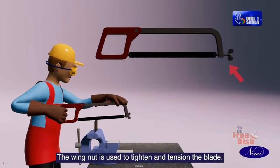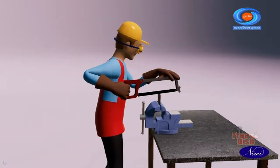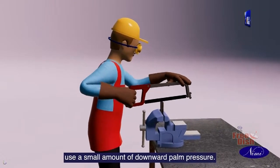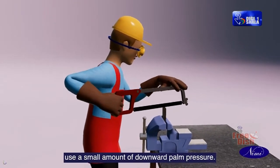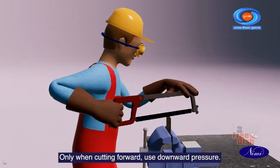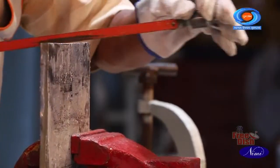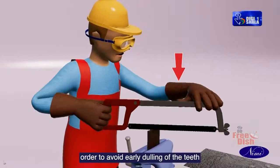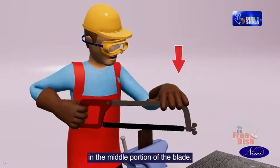The wing nut is used to tighten and tension the blade. As long as only a few teeth are cutting, use a small amount of downward palm pressure. Only when cutting forward, use downward pressure. Use the full length of the blade in order to avoid early dulling of the teeth in the middle portion of the blade.